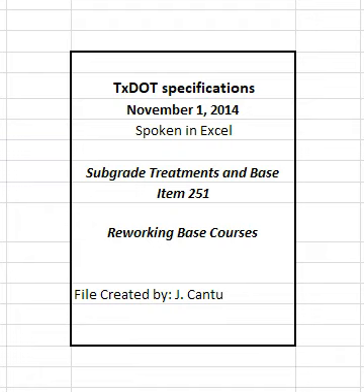4.2.1 Scarifying. Loosen and break existing base material, with or without existing asphaltic concrete pavement. Remove asphalt concrete pavement, surface treatment, plant mix seal, and microsurfacing when shown on the plans and in accordance with applicable items. Prevent contamination of asphalt material during and after removal. When the existing pavement consists of only a surface treatment, do not remove before scarifying.